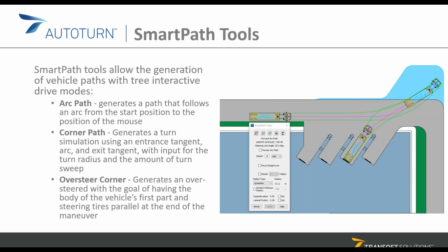That means the vehicle will encroach the adjacent lane at the entry or at the exit, to be able to clear the curb or make sure the trailer doesn't go over the curb. So all these three tools, you'll find them there as a set in AutoTURN, and depending on the design scenario and the design vehicle you're using, you may want to use one or the other.